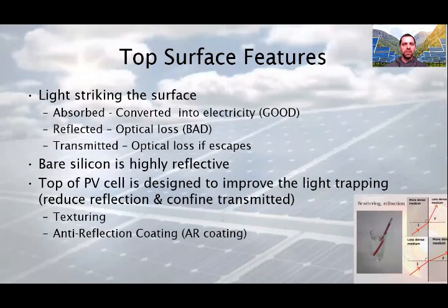We know that bare silicon is highly reflective, and most residential solar systems consist of silicon solar cells. So the cell itself reflects light. And of course, the front of the solar cell, the glass layer, can reflect a lot. Because of the different refraction index between the air and the cell, there is reflection on its surface. Refraction can be seen in the right bottom corner.